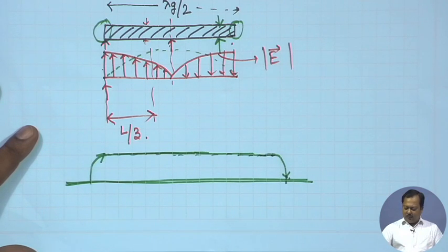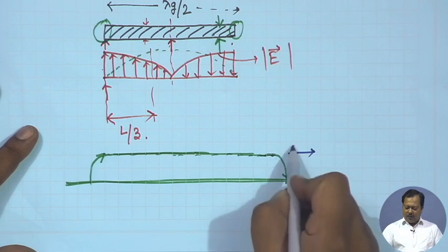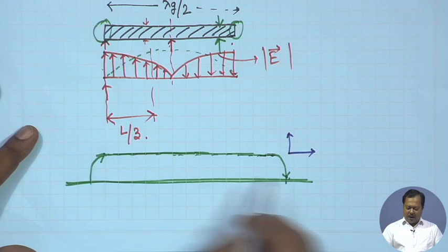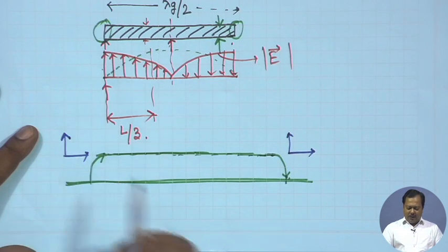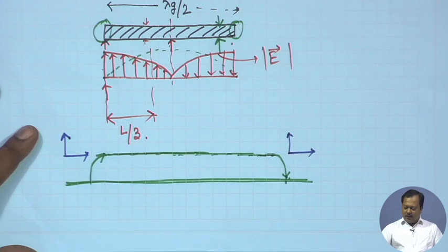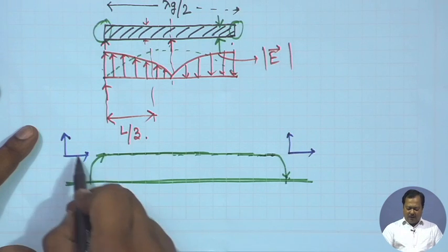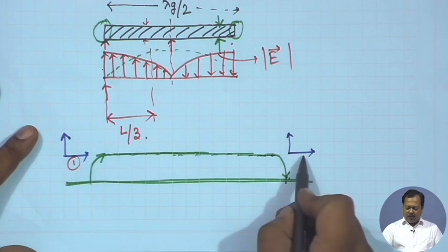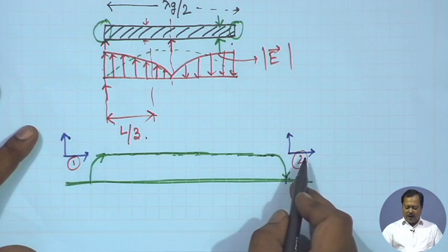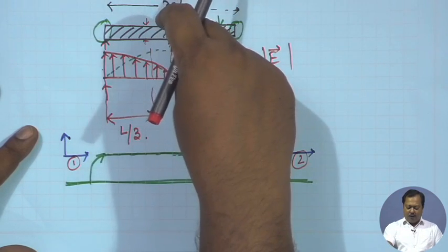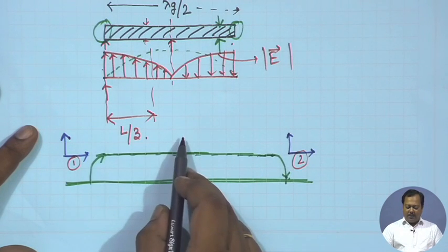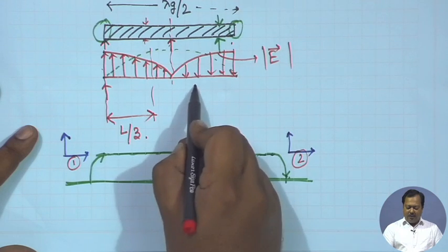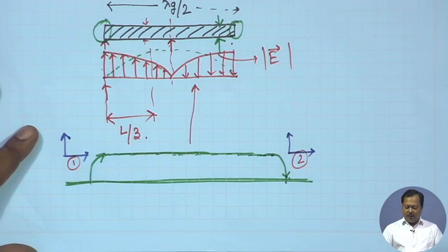Now, I can represent the fringing field along two orthogonal axes. In that case, we see that these two electric field components, let us say this is 1 and this is 2, are in the same direction looking from broadside, and we will have maximum radiation intensity in the broadside direction from these two fields.